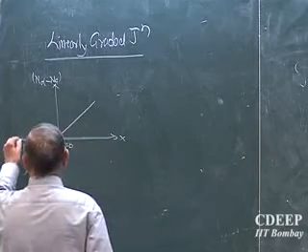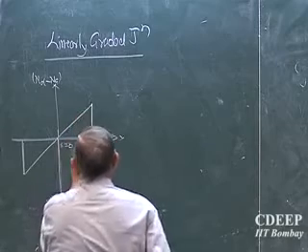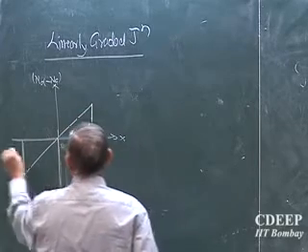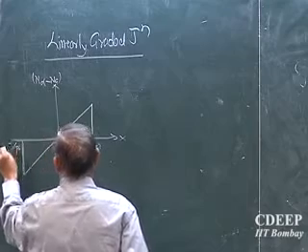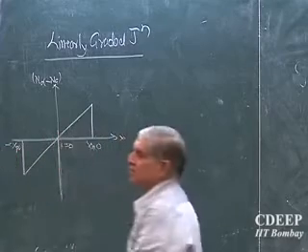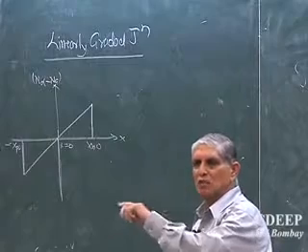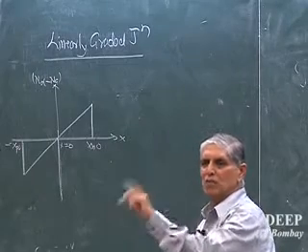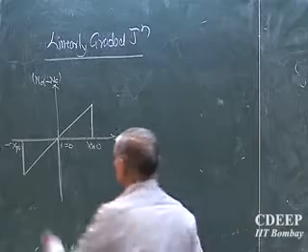Let us say for some reason at zero bias they reach a value of xp0, xn0, and after the same process, some carriers go from P to N, some carriers go from N to P, ions are exposed.